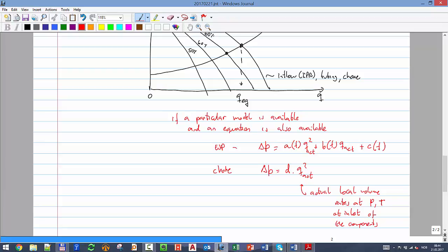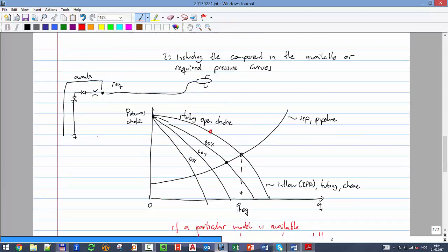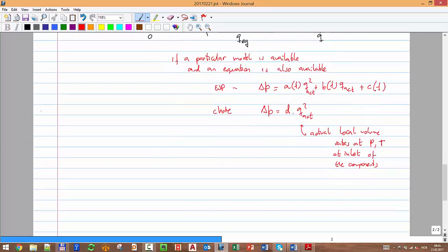And remember that everything, for example, we had flow in the formation, that's based on velocity, right? Darcy law is based on local velocity, so you need local rates, right? We will see flow of gas in the tubing also depends on local rates. And multiphase flow also depends on local rates. So every physical principle of pressure loss in every part of the system is based on local rates. What we need to put later is that conversion parameter from standard conditions to local rates. Okay, just keep that in mind for the future.